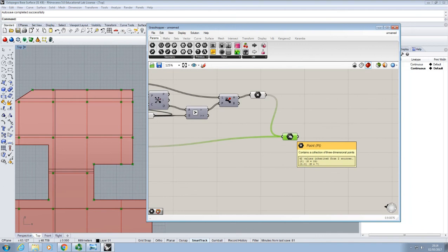So one little thing that Grasshopper likes to do to annoy you is that sometimes these things are actually in data structures, but even if they're in a data structure which has only one branch, it won't necessarily display that as a tree. So it'll only show you the double dotty lines if there is a branch in it. But that doesn't necessarily mean that it's in a compatible data structure. So for example, here we've got two flat lists coming in, but if we hover over that point there, we can see that one of those has come in as one branch with just an address of 0. The other set has come in as another branch with an address of 0, 0, and because they're in separate branches, as far as Grasshopper is concerned, it's not merged, which maybe you assume it would have done.